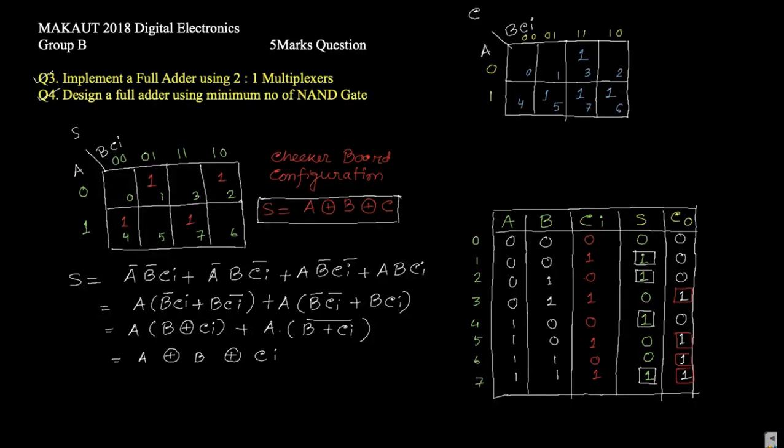So now make the groups in the Karnaugh map. We can make 3 groups. One is this group taking two 1s, another is this group taking these two 1s, and another is this one. We cannot take three 1s; if there were 4 consecutive 1s we could take them. The yellow is the first group, the red is the second group, and the green is the third group.